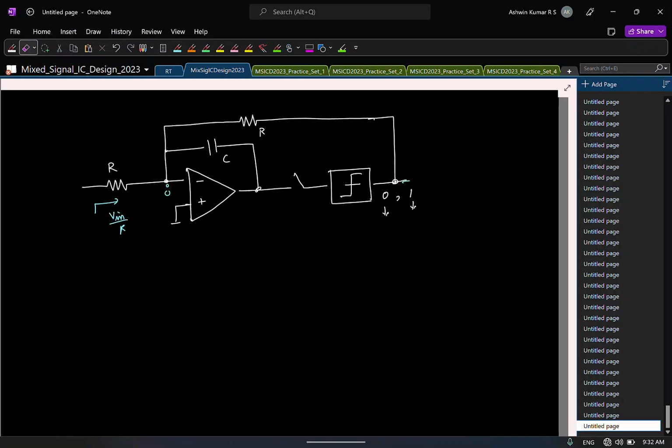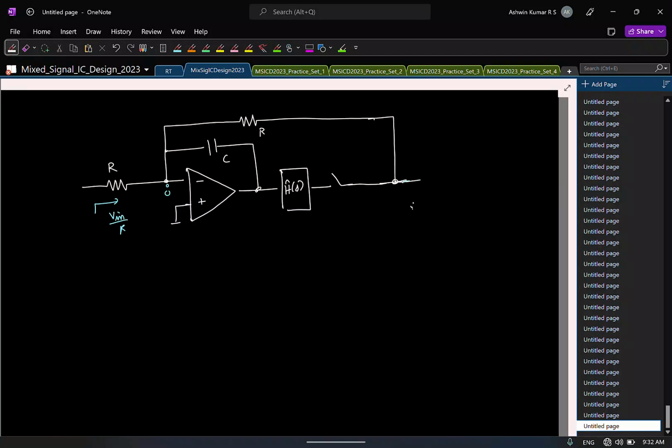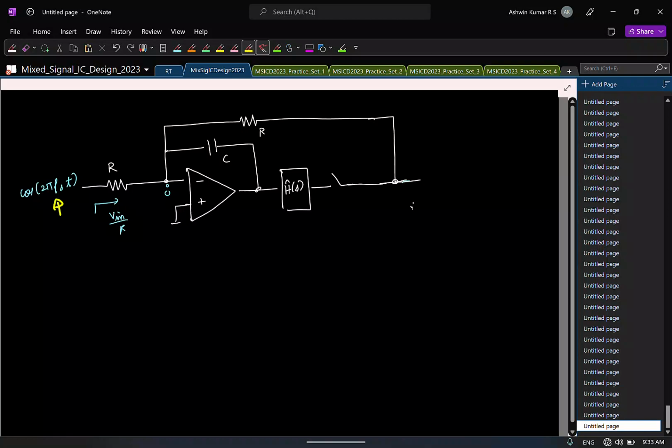Right. So again, I'm looking at signal property. I'll not consider quantizer and all. And remember, I have just taken one integrator, but you can have a higher order filter here, let's say some h hat of s, and then doing this. Cool. So let us say now I am interested to find if I apply a sinusoid at a frequency, let us say Fs, at the output, I am interested to see if this will alias. I mean, to what frequency can this alias back? To 0, which is DC, right? So I will see if there is anything that can alias back to DC.